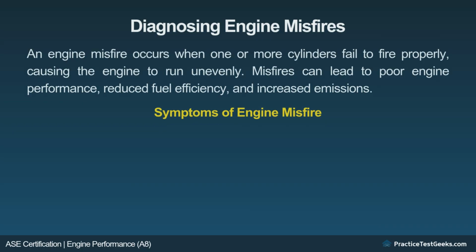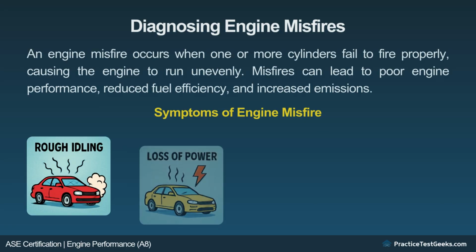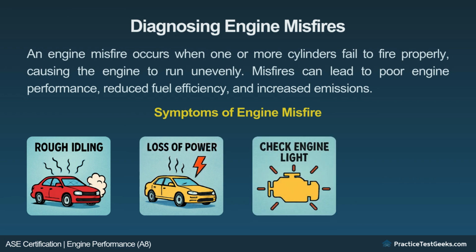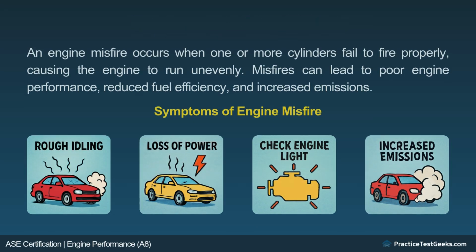Symptoms of engine misfire. Rough idling. The engine may shake or vibrate when idling. Loss of power. Acceleration may be sluggish or uneven. Check engine light. The check engine light will typically illuminate, often accompanied by a misfire-related DTC. Increased emissions. Misfires lead to incomplete combustion, increasing exhaust emissions.